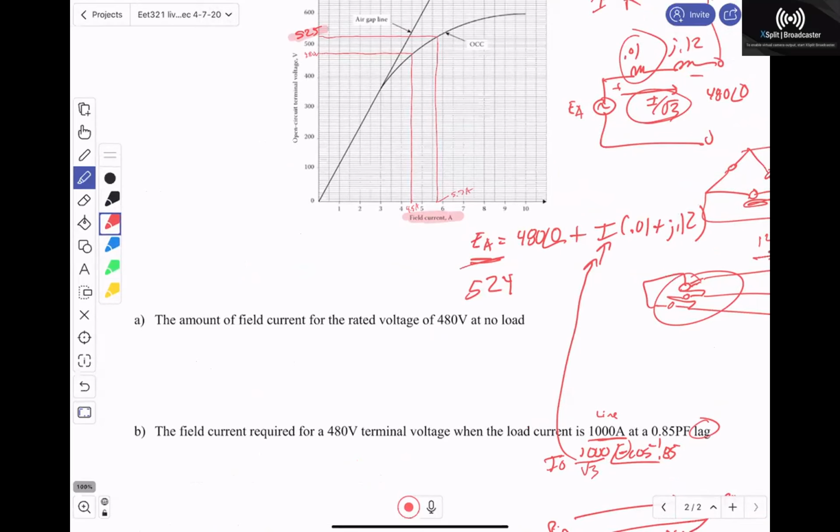So that's what the no load voltage becomes, even though I'm trying to say it's fixed at 480 volts. I haven't adjusted the field voltage. So if I'm just connecting a generator to a single load where there's no other generation, it bumps up almost immediately to 525.